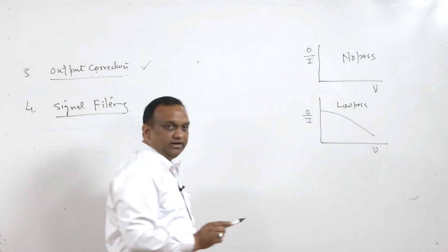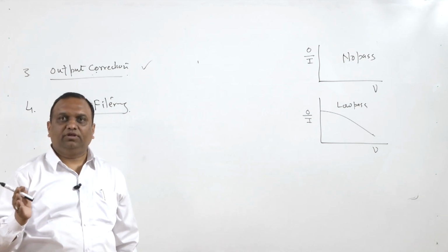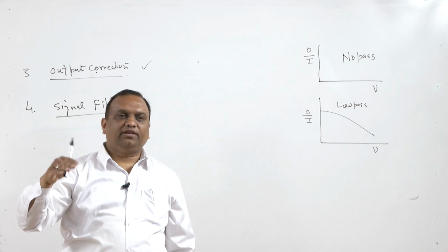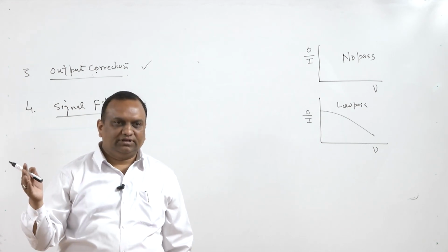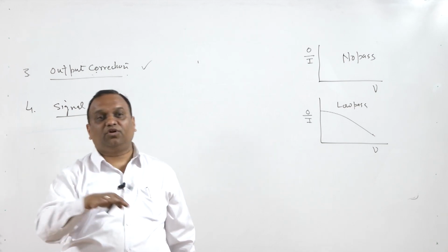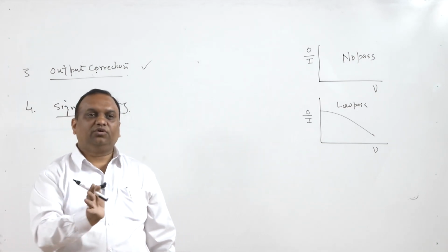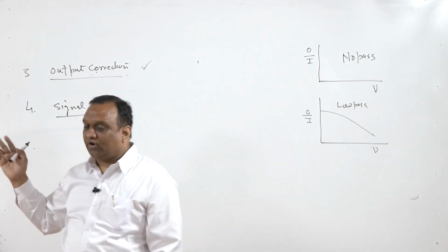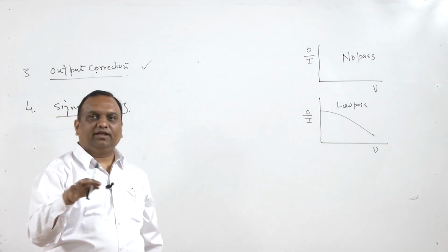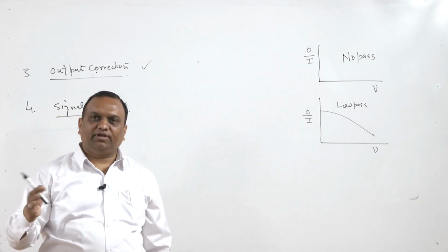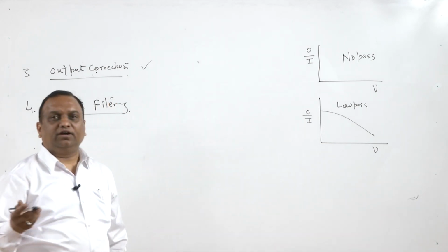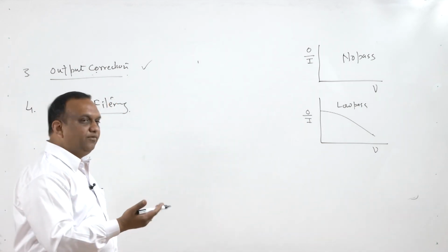Suppose there is an interference of 50 hertz cable. So just provide a low pass filter of 10 hertz. The filter will allow only frequencies of 10 hertz or less to pass. This is frequently observed: the passing cables, they interfere in the act of measurement. So you provide a low pass filter of 10 hertz or 40 hertz, then the 50 hertz will be filtered out.